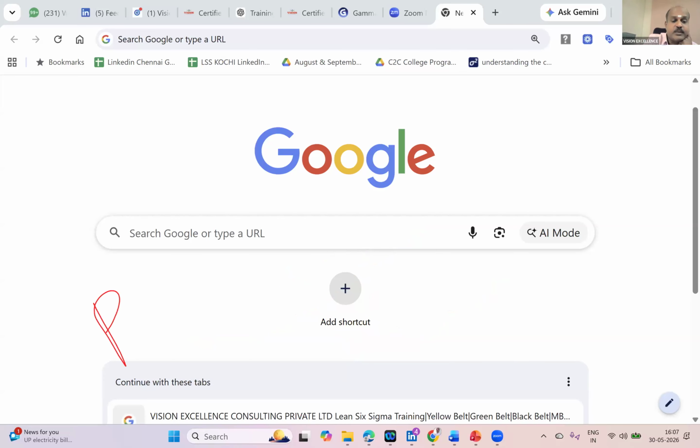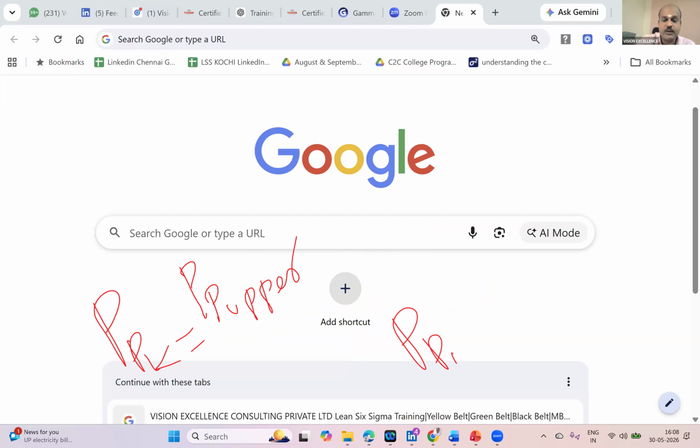Now, same logic. PPK will be equal to PP upper. You know why? You know when? When the process is experiencing a shift rightwards. When the process is experiencing a shift leftwards, in such a case, PPK will be equal to PP lower. That's all.